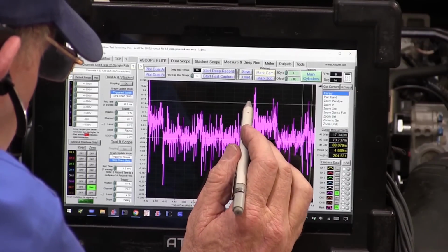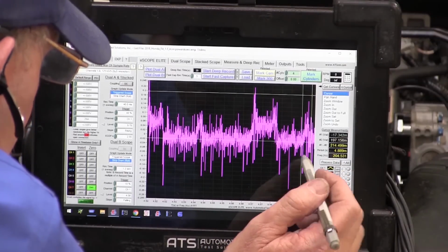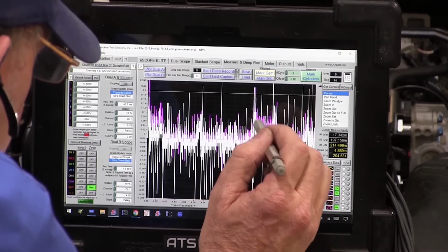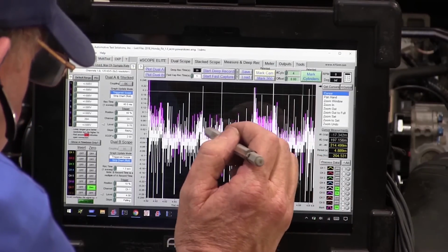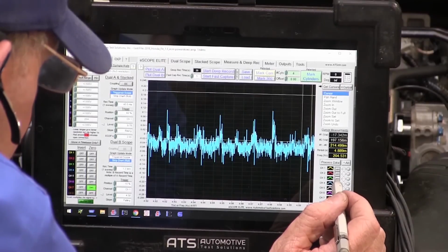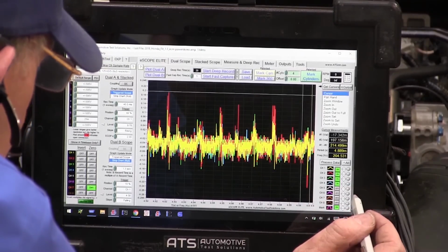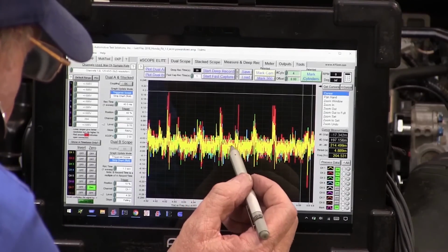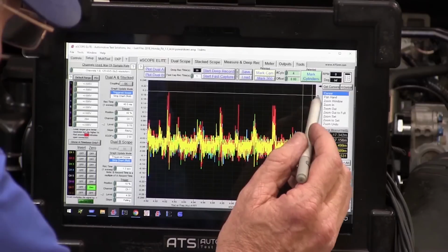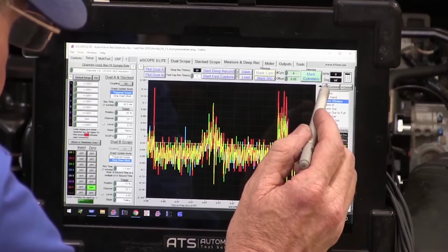This is a high point. We exceed our limit. So the purple's been moving more than I'd like to see it, and the white's moving. I think both of these have to do with the throttle, because none of the rest of these quite have the same look. You can see where we got stuff turning on and off here, and that's normal when you look at ground for the scope. That's nothing to be alarmed about right now.